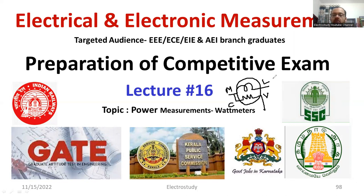There is one more constant that is known as wattmeter constant. You can represent the wattmeter constant by using the letter K. To get the accurate value of power, we use wattmeter constant K. The formula to calculate wattmeter constant is V selected into I selected into power factor by full scale deflection. Full scale reading or full scale deflection. Correct. This is the formula for calculating wattmeter constant K.